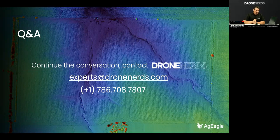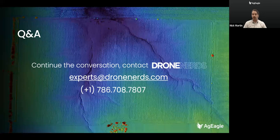Good question here. What are the deciding factors to choose the Altum PT camera over the RedEdge-P? Yeah, the big one I would ask a customer is, do you need a thermal band? So our Altum PT uses a thermal camera from FLIR. It's a fantastic option. Not everyone needs thermal. Thermal and long wave infrared is really good at measuring biomass, and the physical reason is that a thermal band will penetrate multiple leaves.